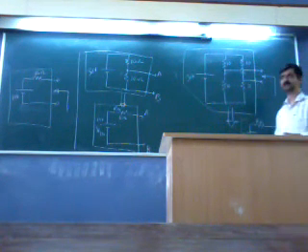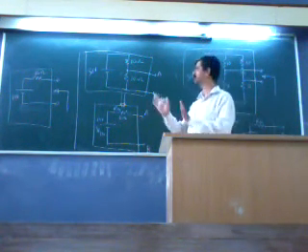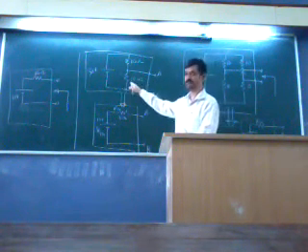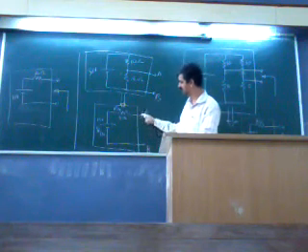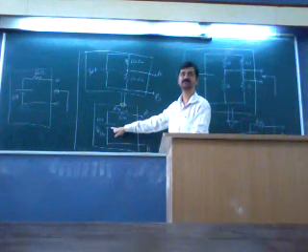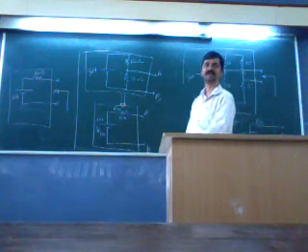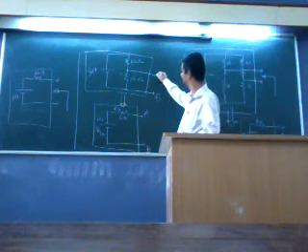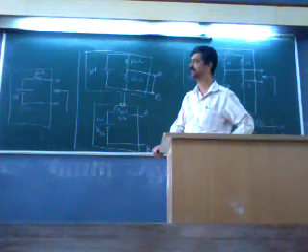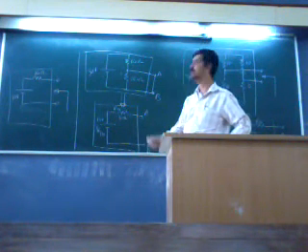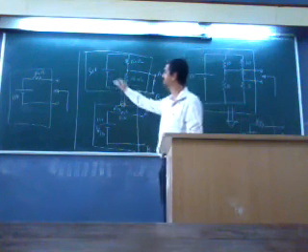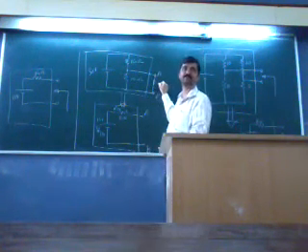The answer is simple. Consider the open circuit case, meaning don't connect anything. What voltage is it giving? 15 volts. If you don't connect anything, to have 15 volts here, this must be 15 volts. Then connect a short. How much current will flow through this arm? 3 amps, because 30 upon 10 is 3 amps.